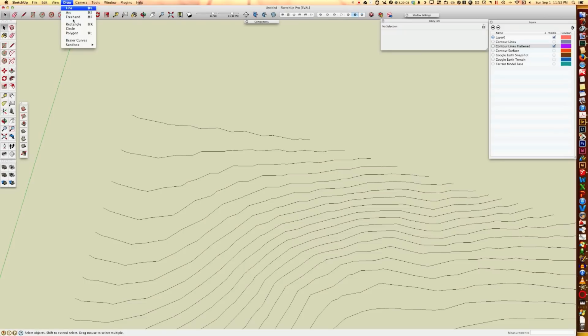So under your draw tools, you'll have Bezier Curve. And Bezier Curve is a mathematical curve. It has a description of a start point, an end point, and radii of curvature. You can see down at the bottom it says degree of curve 3, and you can use either 3 or 4. That's going to change the number of points that you put in. Usually 3 is enough. And you'll see it automatically will snap to points, so I want to grab that end point and then grab the other end point, and then we start to drag. We do 2 more points, and that creates our curve.